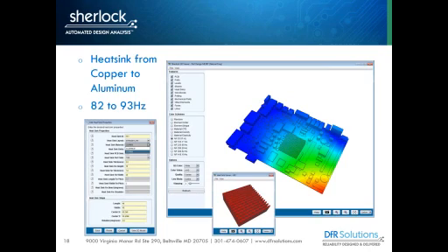And now I could do a little bit more. I could change the fin or change the base plate thickness, anything necessary to reduce the mass of that heatsink to see how it affects the natural frequency. But looking at this plot, we can definitely see we still have a high deflection area at the bottom corner.